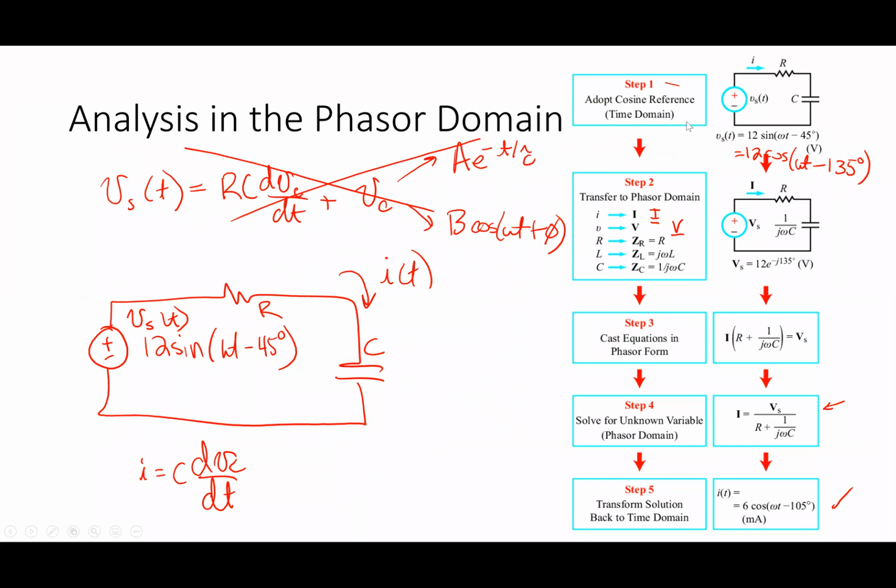So what you'll hear me, and you'll probably hear Yahoo as well, use this term time domain, which is to say that if I have a circuit, I have a voltage source that's hooked up. The voltage source could be a function generator, or the audio output of your phone or whatever. That's a voltage source, okay? Hooked up to an RC circuit. And in this case, as I've said a couple of times, if I want to be able to solve this thing, I have to do a differential equation, right? That's the only way to figure out the voltages and the currents in that circuit.